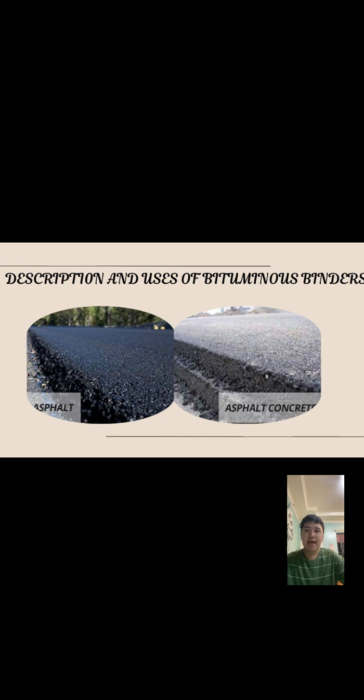And the asphalt cements. Asphalt cements are derived after the separation of lubricating oils from crude petroleum. These materials are semi-solid hydrocarbons with specific physical and chemical properties that make them effective as cementing agents. Due to their high viscosity, both the asphalt cement and the aggregate must be heated before mixing for pavement construction.